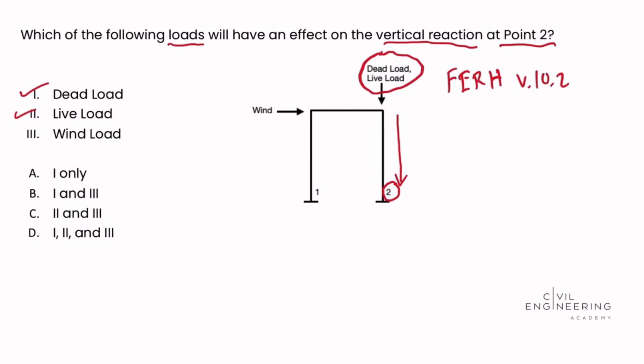Next, let's look at this wind load, and it's a lateral load applied to the structure. This lateral load causes something that's known as overturning. We hear a lot about overturning in civil engineering, especially in structural engineering. This lateral wind load applies an overturning moment to the structure and will force the structure to want to make a motion like this. And this is that overturning motion.